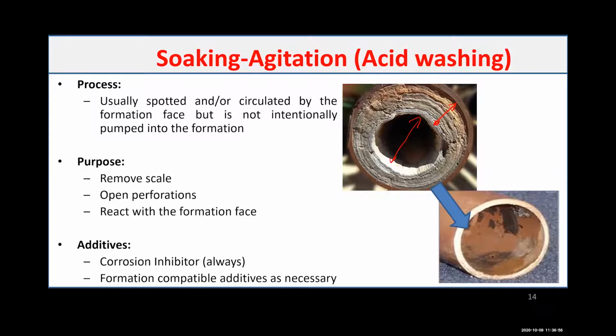You will be able to remove all the scale. Also, you'll be able to open the perforation. Some of the scale also stays in the perforation and plugs it, so you will be able to clean the perforation. And if there is any scale in the formation face, it will be removed.